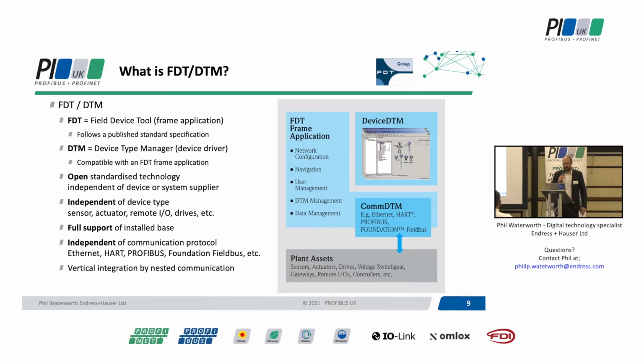It's an open standard technology. It's independent of system supplier or device manufacturer. It's independent of device type as well, so drivers are written for sensors, actuators, remote I/O units, drives, etc. And it's communication protocol independent. Obviously, being at a PI event today, it works with PROFINET and PROFIBUS, but you're also able to communicate to devices on many other protocols.